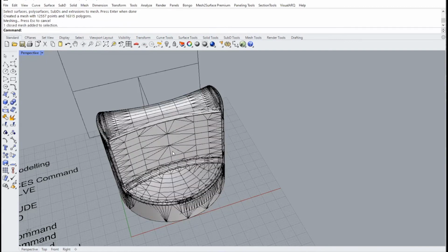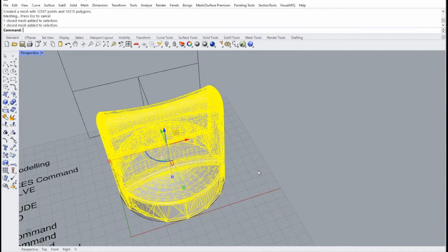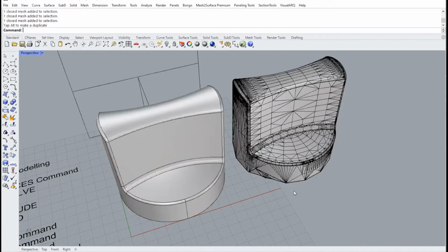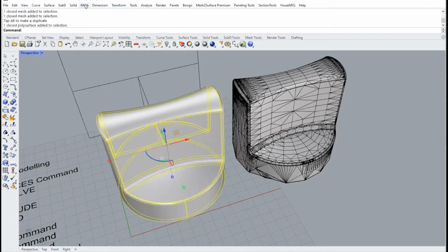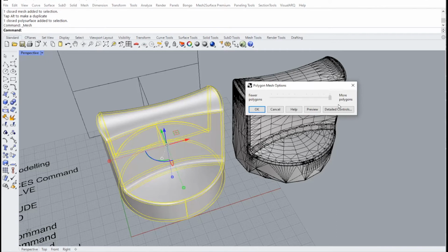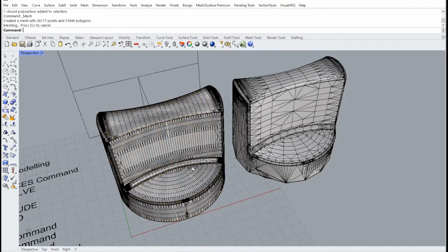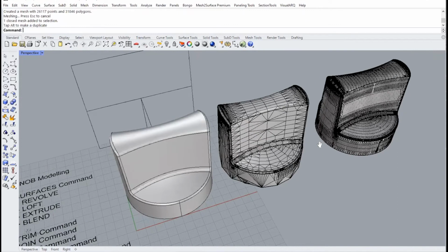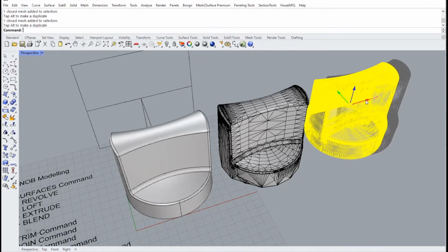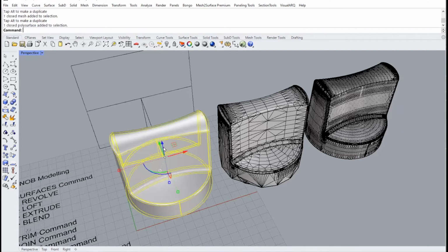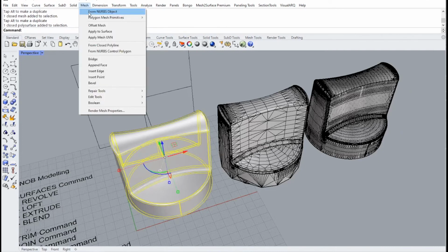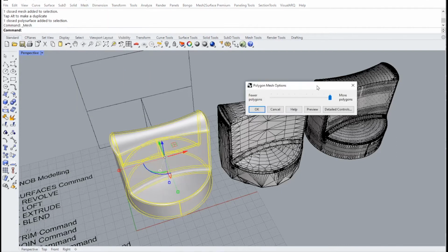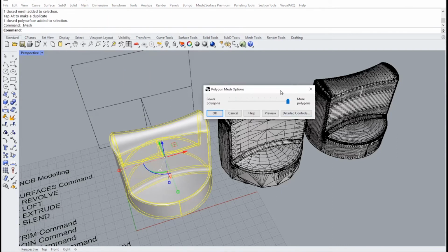It created a mesh within the model. So what you do is pick the selection and drag the mesh out. This is fewer polygons, and I'm going to select this to make another mesh, but this time around more polygons. Say okay. Select the mesh again and drag this up. This seems to be the fastest method, if you ask me, and if you do not have time to consider the other options, then make sure that you have more polygon counts for printing or for machining.